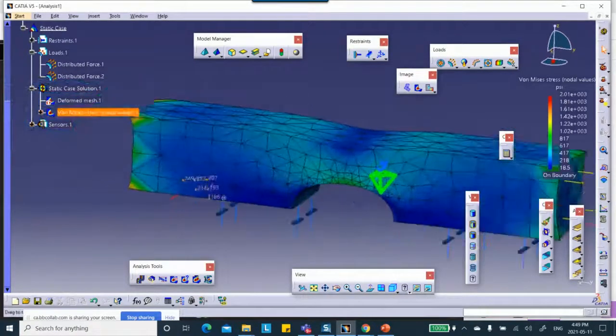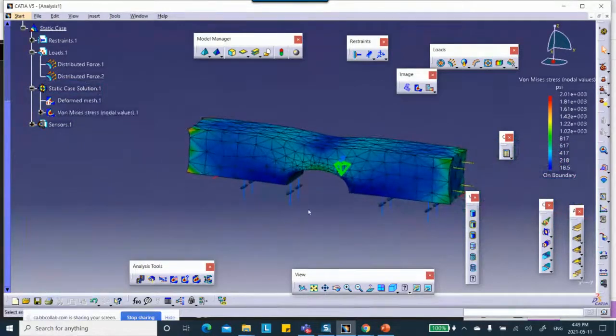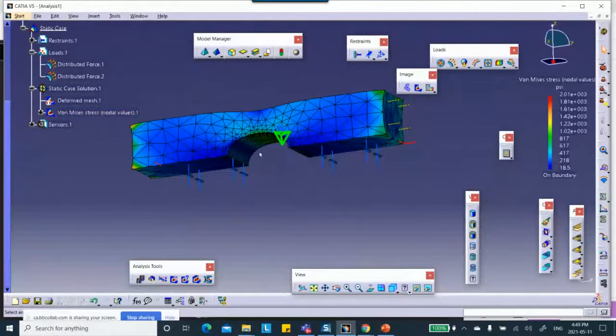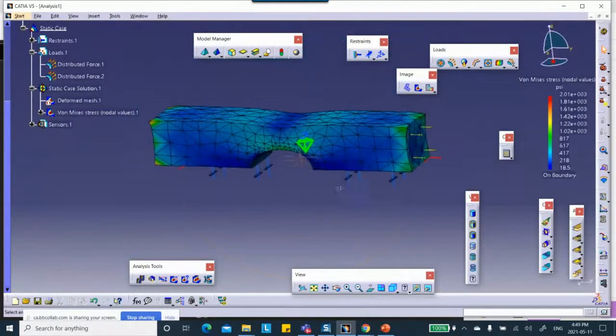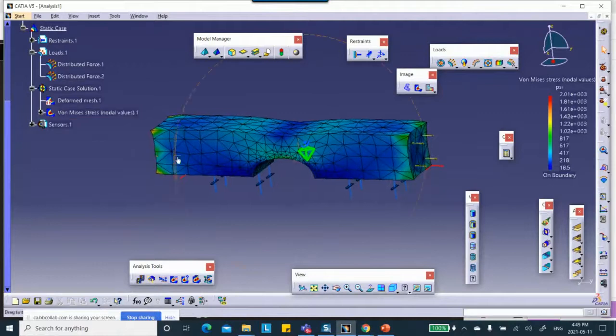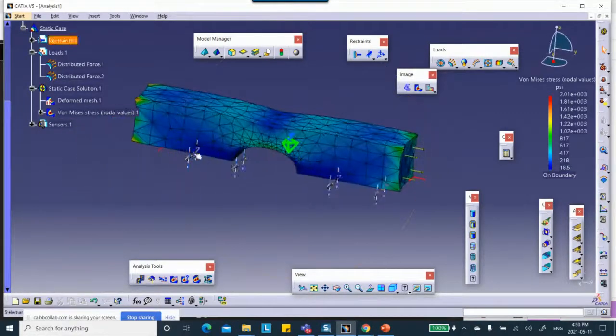The biggest stress shows on these corner points, which are totally fictitious. It's because of the boundary condition. It overwhelms the red stuff here. The red stuff should be there. Okay? Now, this is fine. Give me 2 minutes and I'll let you go. Or 1 minute, actually. I want to see my stress here because I know that these red stuff are killing it and they're totally useless.